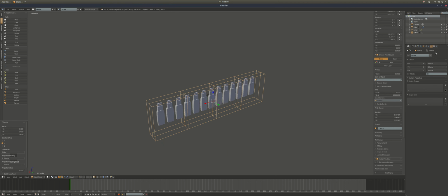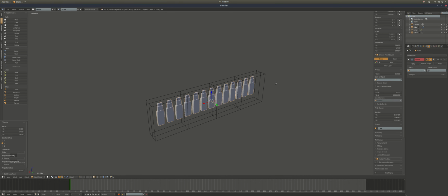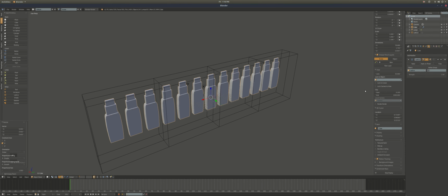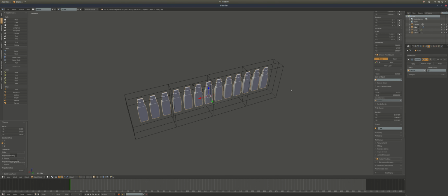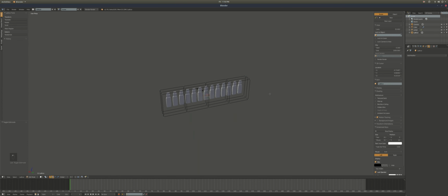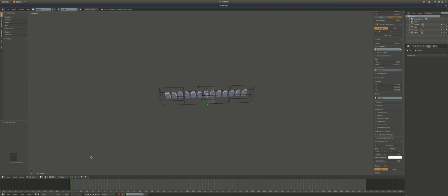But okay, say that I have the resolution that I want on my lattice. I go back into this object, and I see the modifier lattice here, because whatever you applied it to, that's where it's going to show up under the modifiers, so you have to click it. I'm going to select the lattice, and now when I select the actual lattice and I go into edit mode, I can, let's see, box select, and then down here, just to kind of show some things you can do, I'm going to enable proportional editing, and I'm going to do a sphere.